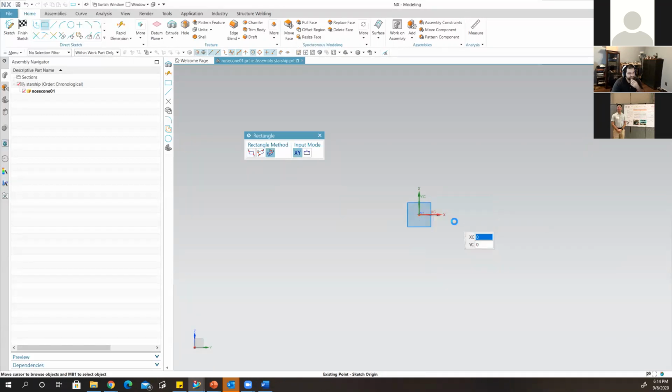click the 16 point. Then I'm just going to do it 3 inches. And then I'm going to tap twice or just once. And then on the angle portion, I'm just going to keep it at 0. That way it doesn't move around. That way it's a straight line at 0.